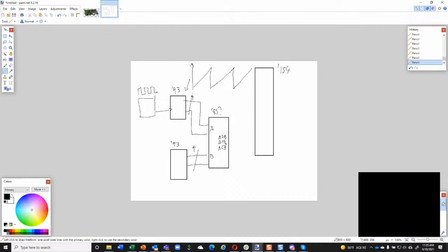And this counter here, I'd hook up an up button to the up count. These are up-down counters. I put a down button. I'd have a reset circuit, and these could also preload a value of 4 bits. So I could have a connector, or this could go off to some other system, and it could remotely preset the value. And the output of this comparator, the B, would be whatever the set value is, and pushing the up button would make it go up, pushing the down button would make it go down.